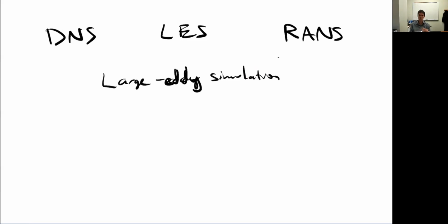So again, particularly important for cases where I need things like acoustics, structural dynamics, or I need to see the time history. Well, I should say we can do time varying RANS, right? It's called unsteady RANS, but we've still averaged out the behavior. In other words, things can change in time. So I can have an airplane that's doing an unsteady maneuver, but at each instant in time, I've averaged out the flow behavior.